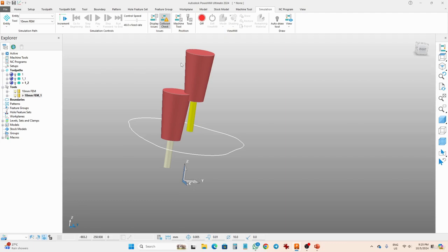You have to check the verification, whether your tool is going to collide with the workpiece, the fixtures, or any other stuff, like accessories such as the C-axis and other rotary axes on the table. We have to ensure that the tool holder is not going to collide with that. So using the toolpath verification, it's done.